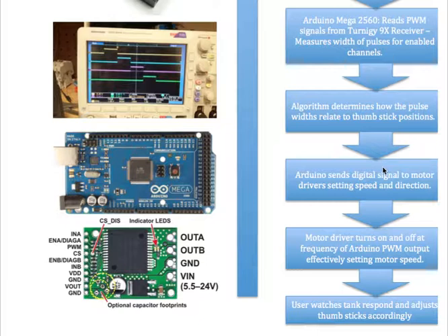In order to tell our motor how to respond, we need some way to interface with it. A common way to control the speed of a motor is to vary the voltage. That is basically the only way to vary the speed of the motor without changing the load or applied current or other more complicated things. So we want to change the voltage to the motor. How do we do this? With our good friend pulse width modulation.